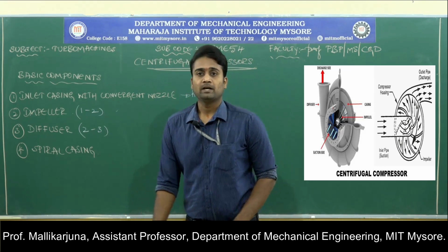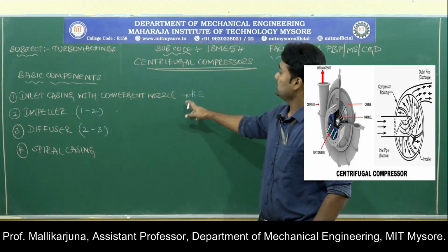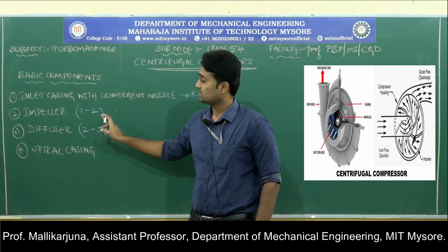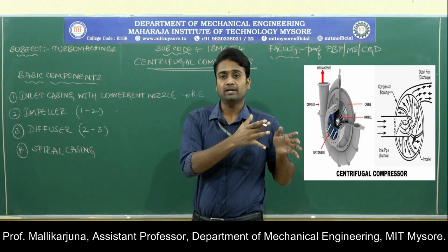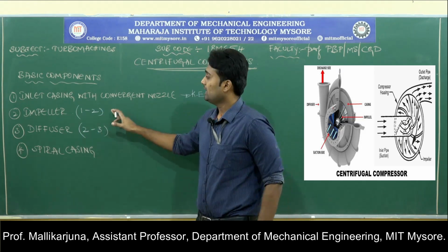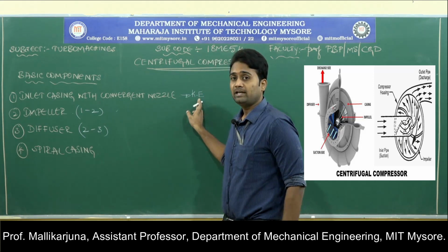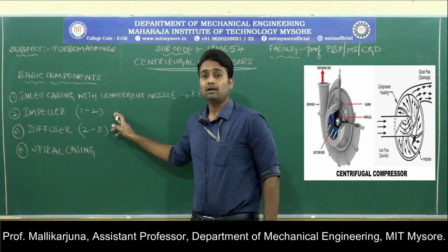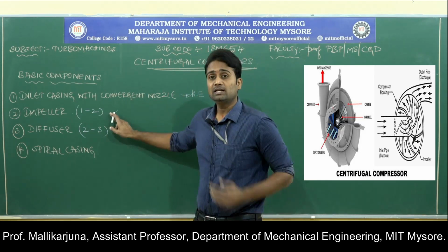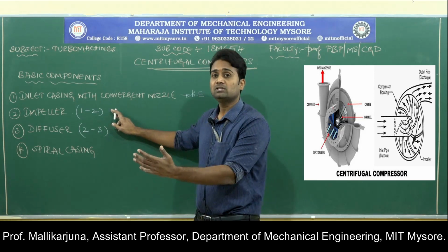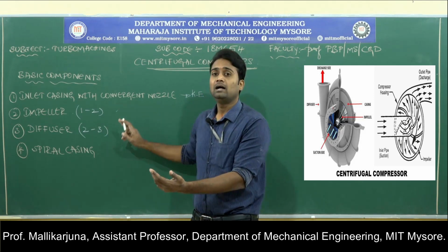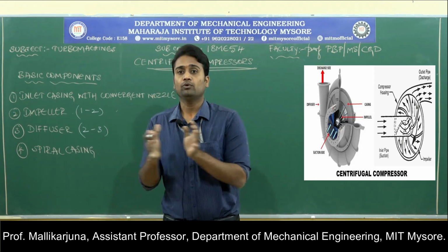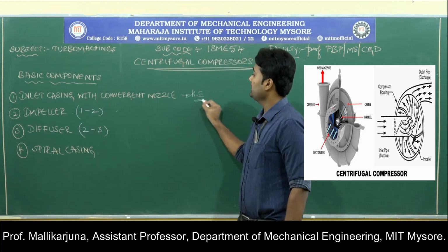Next, the diffuser. We know that in the nozzle the kinetic energy has been increased. With this kinetic energy the fluid has entered the impeller, and then it is subjected to the centrifugal effect. Then this kinetic energy is not absorbed or increased by the impeller. The part of the energy that is developed, the kinetic energy with which the fluid is thrown from the impeller, has to be regained. In the sense, the fluid is moving away now, with the help of kinetic energy.